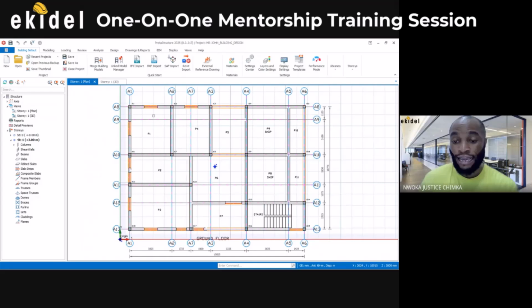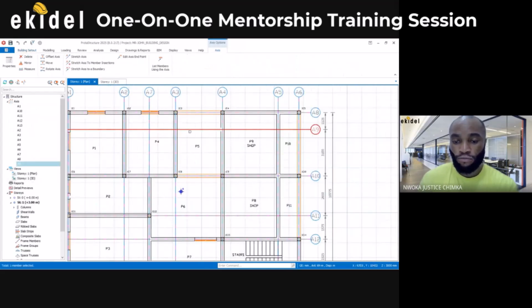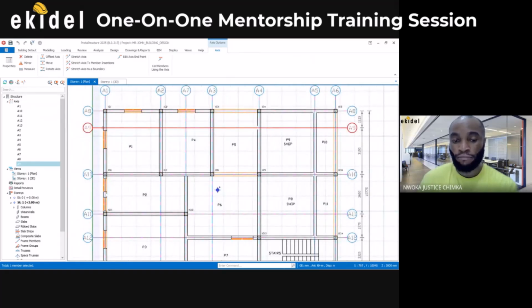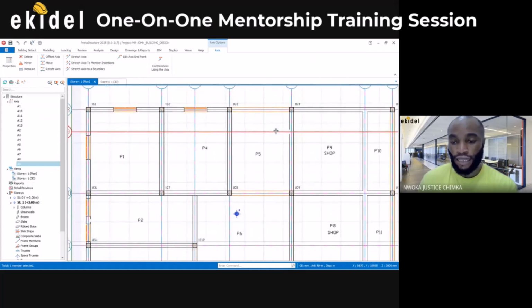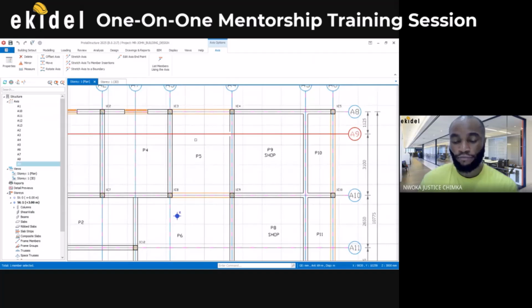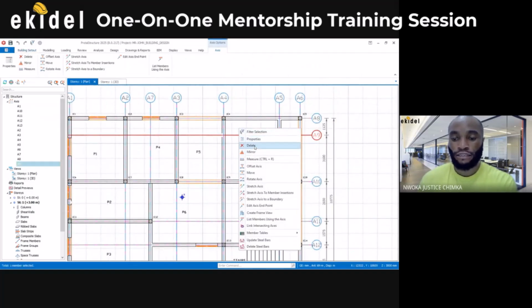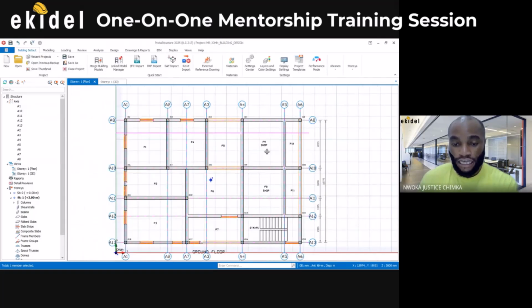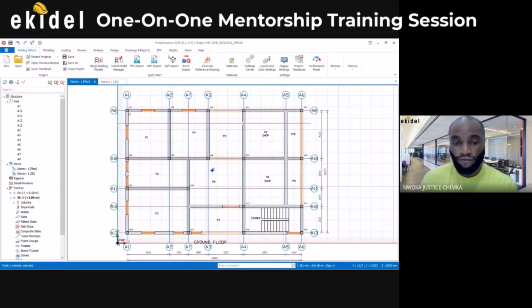But before we do that naming, there are some grid lines that are not giving any number. For example, this grid line 9, AA9, is not pointing to any number. You can see that. That means that we have to take it off because it's not pointing to a column and there is no beam around this line. You can see that there's no wall line. So I'll just click on it and then right click and delete it. Okay, that's fine. That's the only grid left. So just look out for the grids that are not pointing at anything and then take them off.